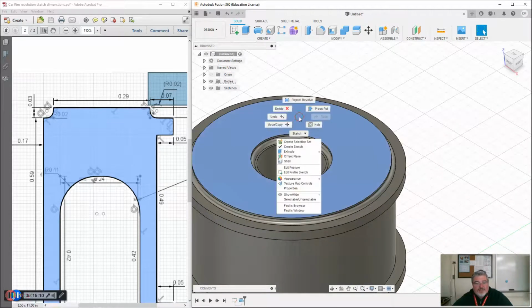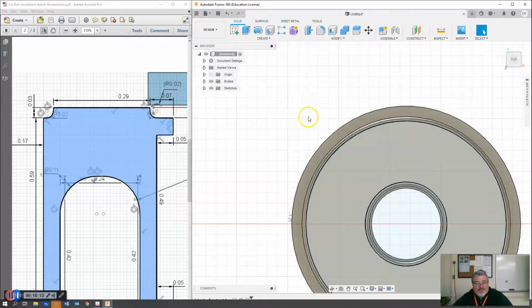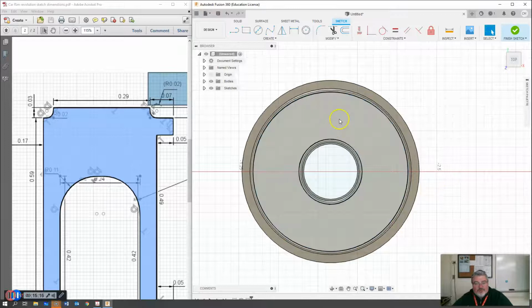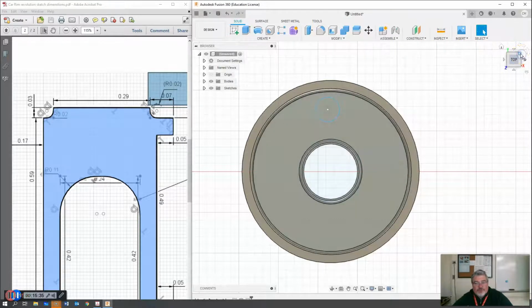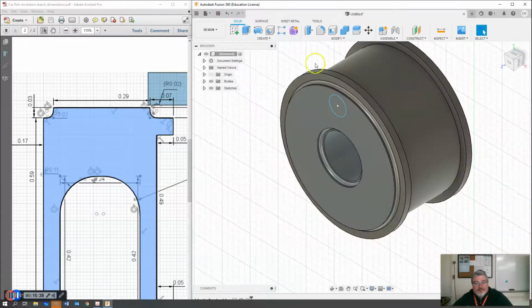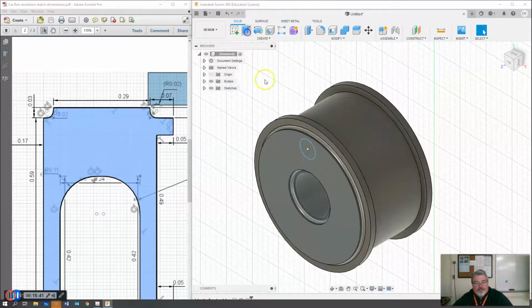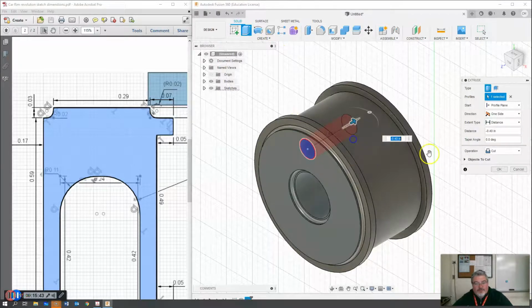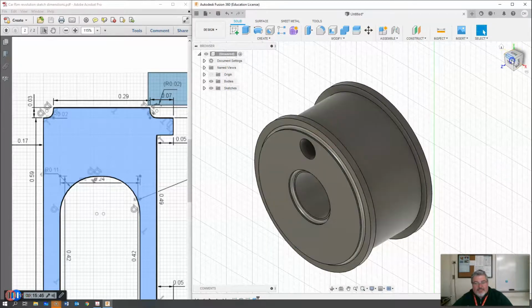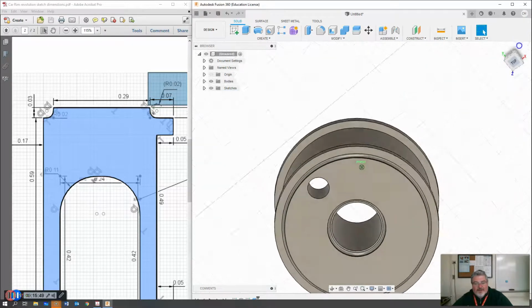So on this surface, you'd create a sketch, and this is where I was showing you in class how to put circles or triangles or your name or whatever you want on here and create a pattern. So let's say I'm just going to do circles. I can create any shape I want. I can use polygons and whatnot. So let's say I just do a circle. And then I finish that sketch. Go back to isometric view. Finish that sketch. I extrude cut this circle so it cuts the circle out of my rim, right?